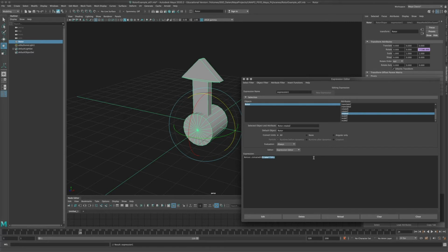So let's change that a little bit. Instead of using those fixed values, known constants, let's say we want to add a number at runtime, which is what you want to do if you're adding an RPM value. So you're telling the thing, listen up, the current RPM is 1000, for example, so please add this number of degrees to the rotor every frame. If we keyframe our RPM, or rounds per minute value, it will start to add larger numbers over time. But in the end, this thing will behave like a real rotor.